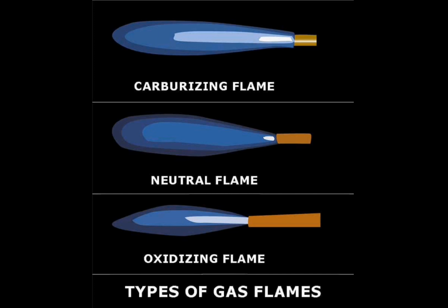Why is it desirable to use a soft flame when welding aluminum? To avoid blowing holes in the metal when the puddle is formed. What determines the amount of heat that will be applied to the work when welding by the oxyacetylene method? Torch tip diameter.